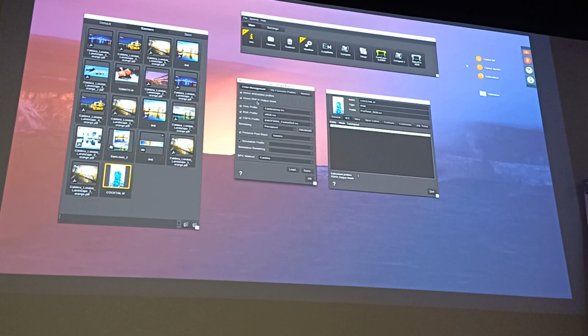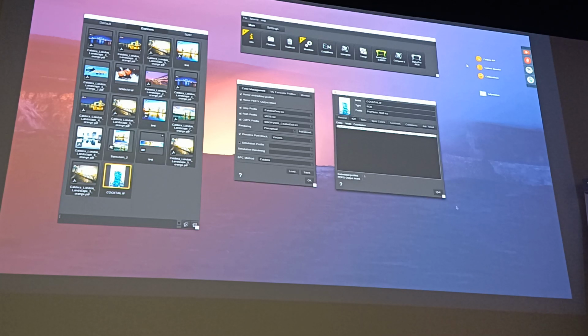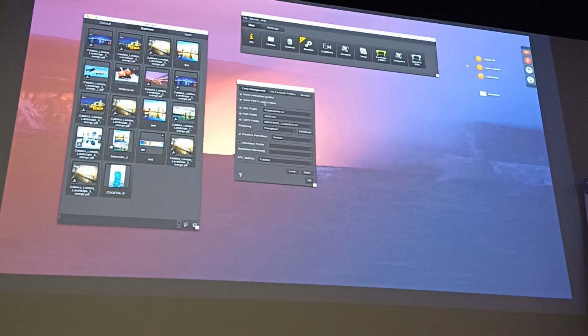Okay, PDFX output intent is only in regard to PDFX basically. PDFX usually contains an output intent, which is for graph 39. So even if there is no embedded ICC profile, you have an output intent, so it will be loaded as the color profile by default. So it's up to you. Usually we keep it activated, but it's only if you are working with PDFX files. Okay, so that was for the global configuration.